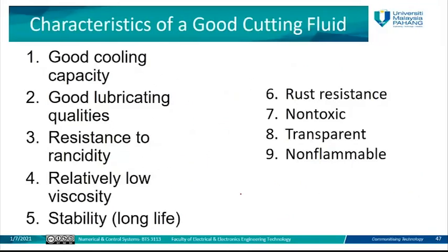These are the characteristics of the good cutting fluids. So it's good cooling capacity, good lubricating quality, resistance to rancidity, relatively low viscosity, stability also, and also rust resistance, non-toxic, transparent, and non-flammable.